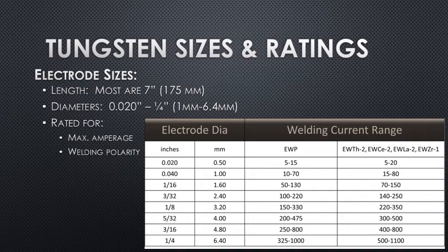This chart here that I've created basically takes the best of both worlds. We have the lowest performance and the highest performance, so we have a total range, and you'll see that pure tungsten has a slightly lower operating range, and again, it tends to form a ball during welding no matter what you do. So usually we would shift over to an oxide-bearing tungsten whenever possible. And again, cerium and lanthanum are my two favorites.